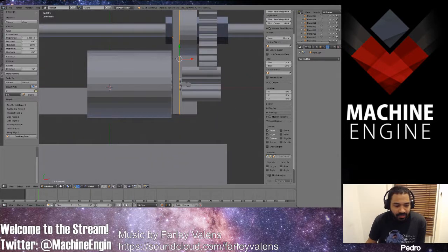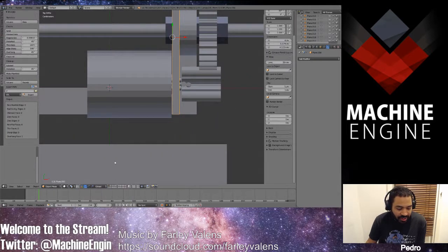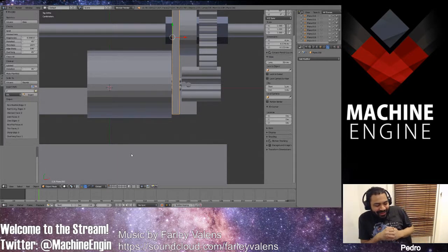As long as you're 0. Sorry, headphone guys. Sorry, I hit the mic. But as long as your non-manifolds and your bad continuous edges are 0, you should be fine.